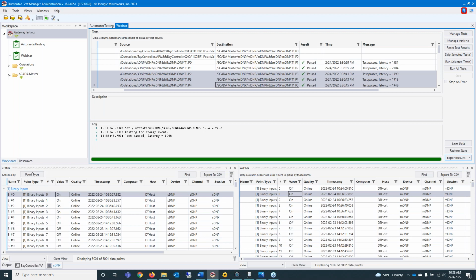I think Jackson mentioned earlier, it's a fairly manual process to go in and map all these points across, and it can be really easy to accidentally put the wrong point in or the wrong destination point or something like that. So you might get values going to the wrong place. In the simulated environment, you can verify all that's done too. Once you've done that all in the simulated environment, you've confirmed that the behavior works, the functionality is there, and that your configuration is proper. When you go and put it into a physical environment, you can already weed all of those out as potential issues if you do run into issues in a real environment.